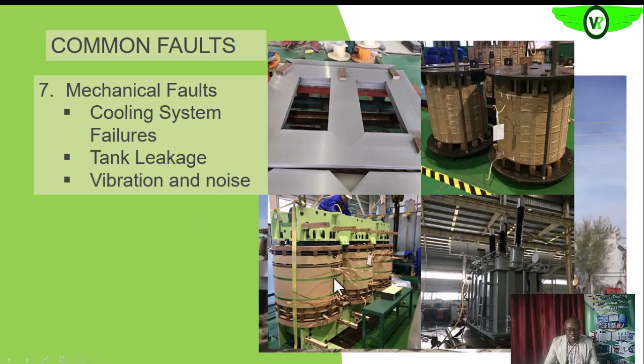Another thing that can cause vibration too is maybe when we have unbalanced magnetic field on each of these faces of the windings in the transformer, which may be as a result of short within any of the winding. So that unbalanced field will result in them not cancelling out, and can also result in vibration and noise. You hear the transformer overhumming, and overloading too can also cause vibration and noise in the transformer. So we want to guard against all of this.